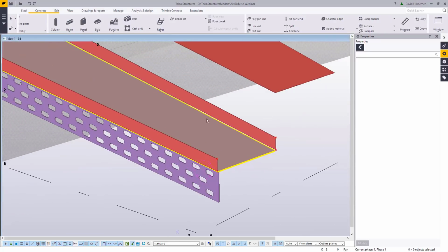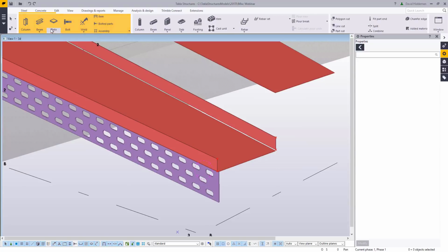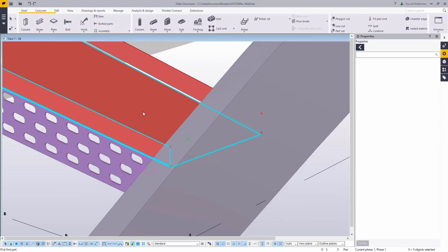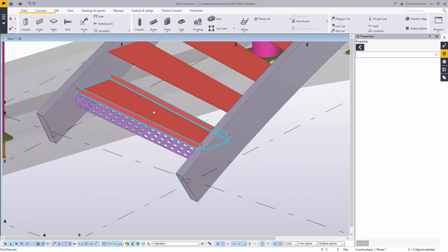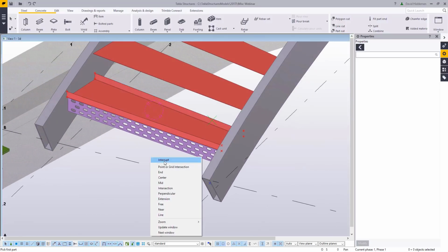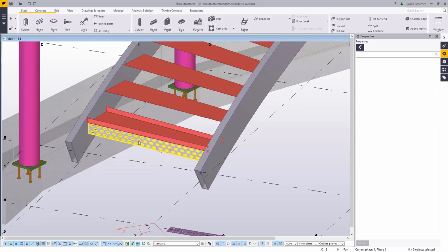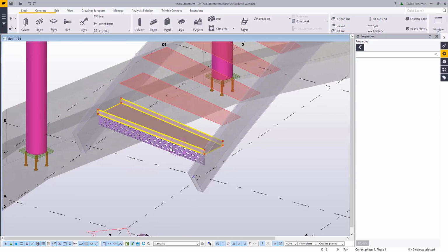Let me use that bent plate tool to join the bottom and sides together. So we'll go to the create bent plate using parts. We'll pick those 2 pieces, and then we'll pick those 2 pieces. Okay, so now that we have that put together, they are still separate pieces. So if I want to reuse them, I'm going to have to copy, copy, copy, copy. And I'd rather not. I'm all in favor of making my life easier.